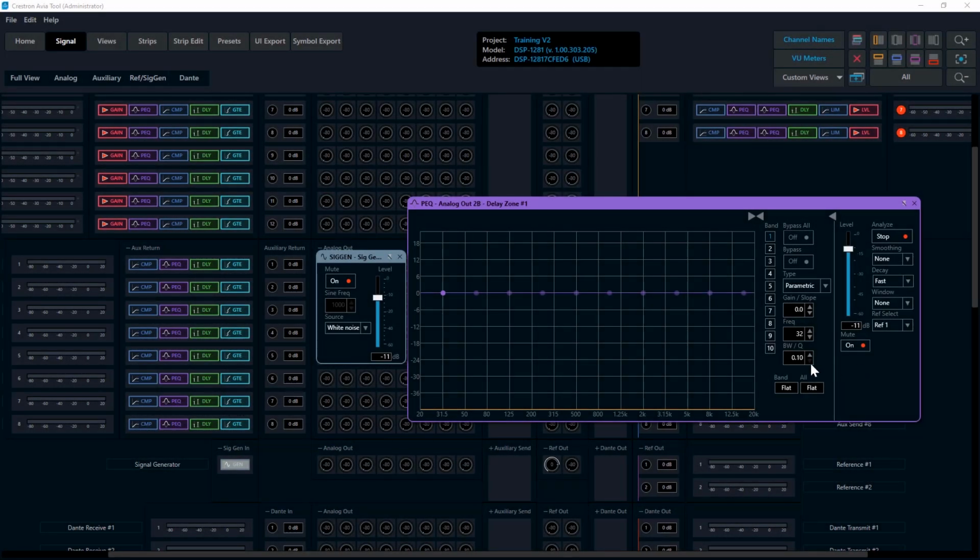First, we should discuss the differences between white and pink noise. You are viewing a direct feed from the signal generator to the analyzer. No microphone. A white noise generator creates a signal that has equal energy per frequency. A pink noise generator creates a signal with equal energy per octave. Pink noise is a better representation of how the human ear hears and is commonly used for system calibration. Just for reference, here's what a 1000 Hz signal looks like.